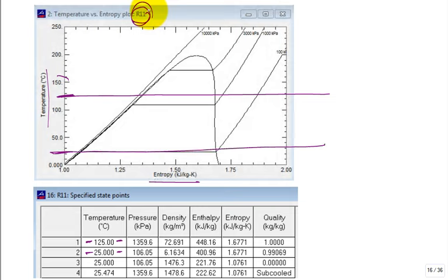Okay? And so you say to yourself, let's just say that we're going to come out as saturated vapor. There you go, state 1. That's out of the boiler, out of the steam generator. Then you're going to pass it through a turbine, isentropic, that would be our best, down to state 2. And from state 2, we'd kick it over to condense it, state 3, pressurize it, state 4, and then heat it up and go through the cycle.